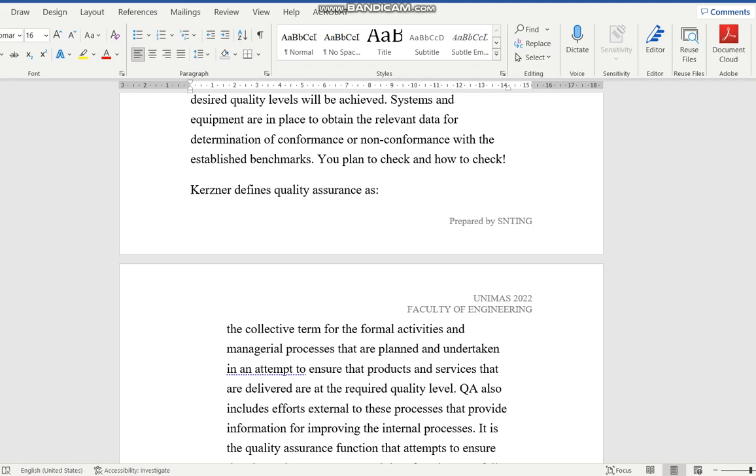So you want contractors to understand that when they do concrete cover, it has to be 25 plus or minus 5 mm, for example. Why? They need to understand why, so that they will voluntarily do it, because they understand that if they don't do it, later on there may be issues with maintenance, issues with the product not looking aesthetically good, or it may reduce the strength and affect other parts of the structure, for example. If they understand it, then they will be more willing to do it, you see.